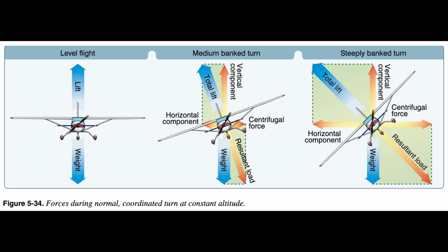If no rudder is used in a turn, the nose of the aircraft yaws to the outside of the turn. The rudder is used rolling into the turn to bring the nose back in line with the relative wind. Once in the turn, the rudder should not be needed. An aircraft is not steered like a boat or an automobile. In order for an aircraft to turn, it must be banked. If it is not banked, there is no force available to cause it to deviate from a straight flight path.